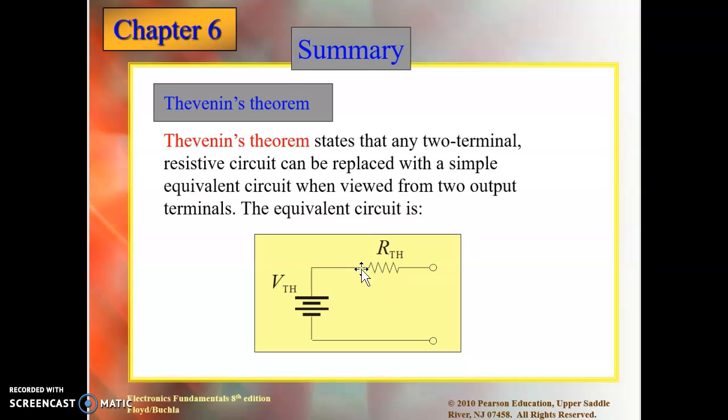Yes, we have buffers in between to cut the noise and to separate different phases of the design, but it's also important that the rest of the system knows what voltage you are going to be producing and what load you are going to be creating. Why? Because we want to avoid loading effects. Okay? So this is the Thevenin.